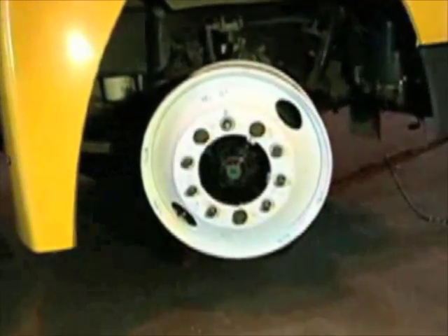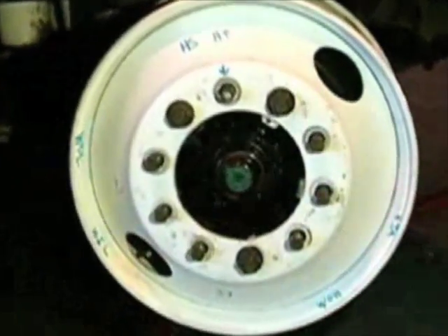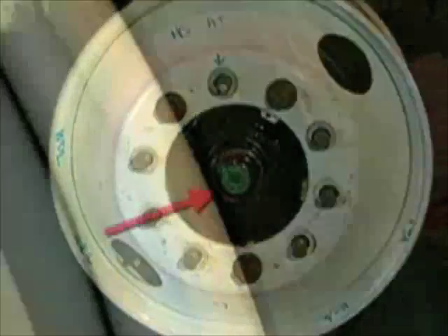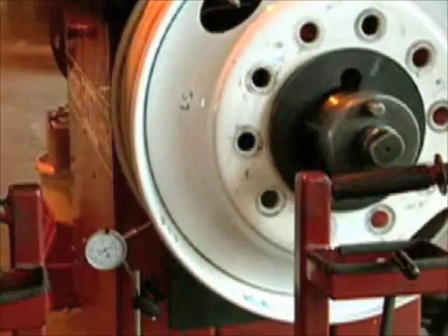Compare the high and low runouts found on the tire and wheel and note the relative position of each. If the high and low readings match or stack up, this may be another cause of your vibration complaint. In this example, the cause of the runout error was due to improper mounting of the tire on the wheel combined with marginally excessive wheel runout.